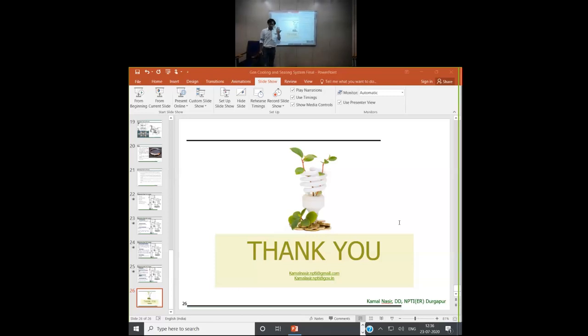But we cannot go to the maximum allowable temperature. The generator is fixed at around 110 degrees centigrade. We have an alarm at 100 degrees and tripping at 110 degrees.